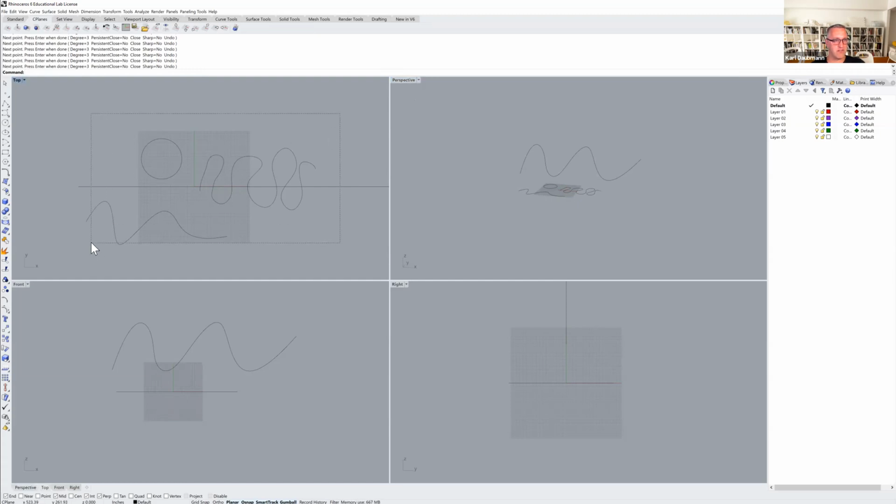So maybe if all of you want to draw, let's make a really simple object. And so come down to the rectangle tool. And there's corner to corner as the default. And so if you click in 2 places, you'll make a rectangle. I tend to always opt for the rectangle 3 points, because that way I can set a dimension and then I can set the other dimension, because it's basically like, what's the width and then what's the height.